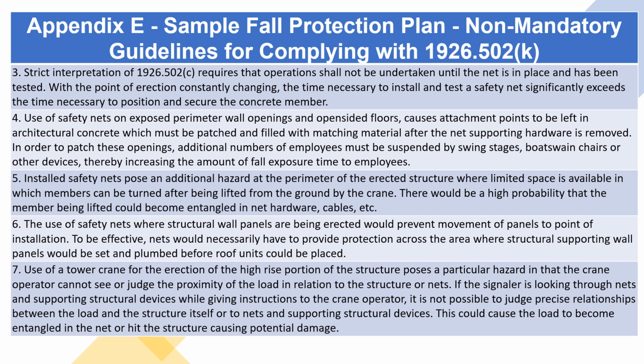5. Installed safety nets pose an additional hazard at the perimeter of the erected structure where limited space is available in which members can be turned after being lifted from the ground by the crane. There would be a high probability that the member being lifted could become entangled in net hardware, cables, etc.